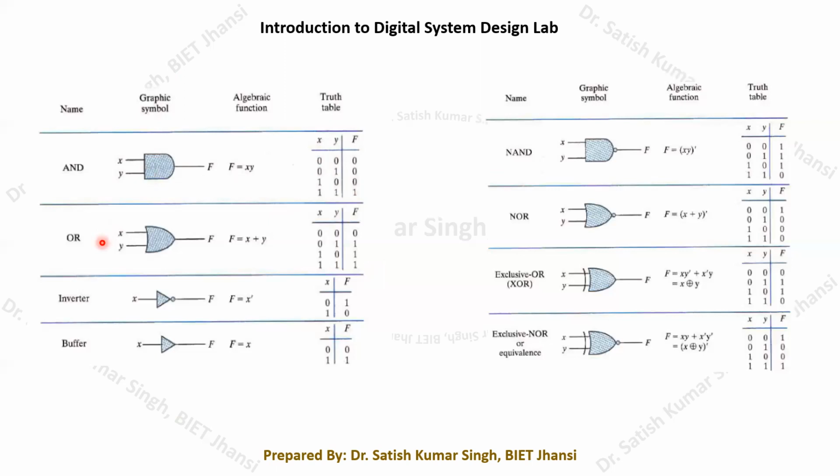You must be aware that the AND gate is also represented as series switches. So it is regarded as a series switch. Whenever we have a particular input at one point, and we want to send it to the other point, there will be two switches connected in series. If both the series switches are closed, then only this input signal can be passed to the output point.